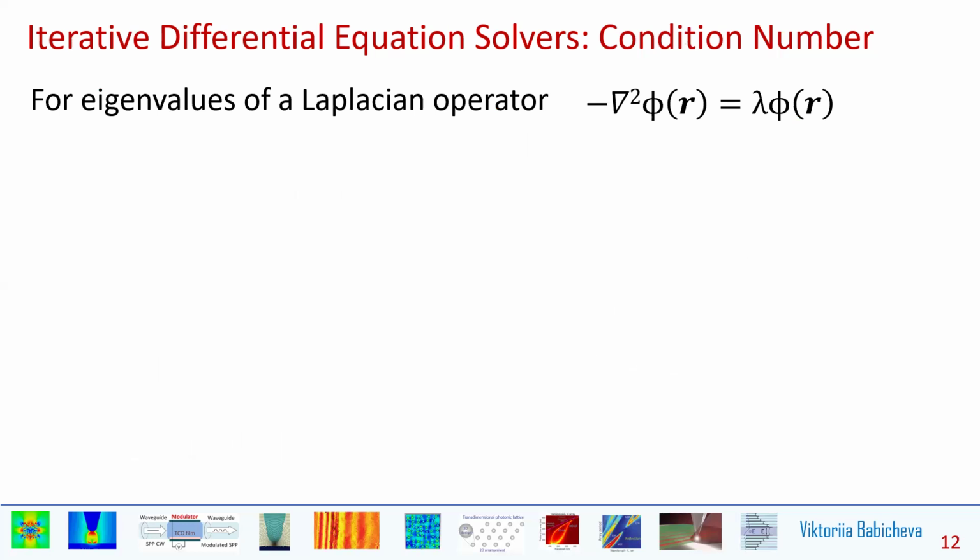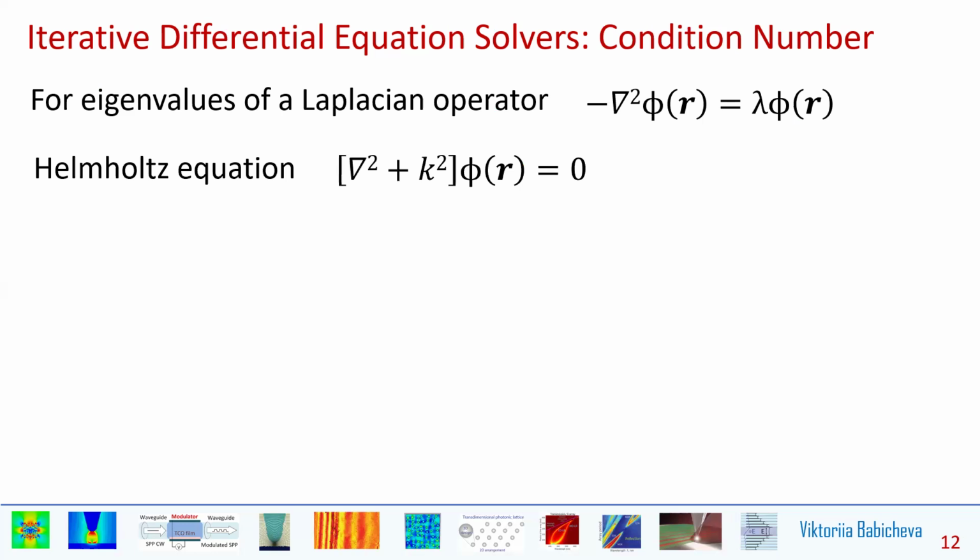We are looking for the eigenvalue of the Laplacian operator, and it is equivalent to solving the following equation. It is also the same as solving a resonant problem involving the Helmholtz equation. For instance, in the two-dimensional case, the Helmholtz equation is defined by this expression, and therefore the largest eigenvalue corresponds to the highest spatial frequency supported by the mesh.